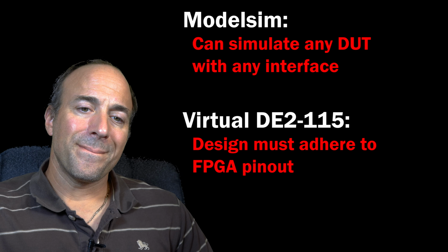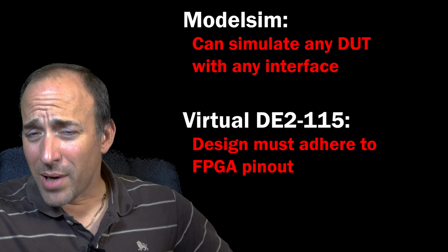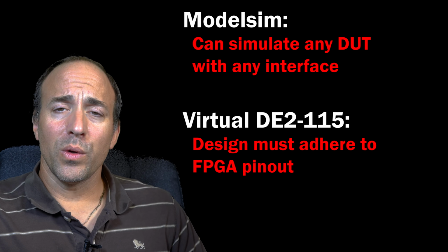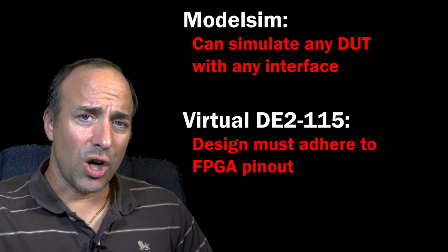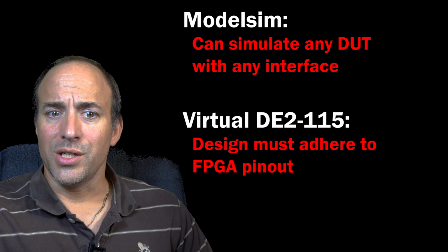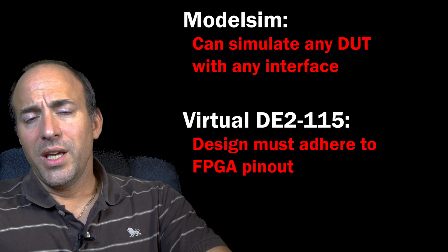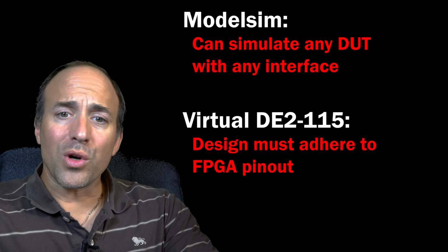However, simulating with Modelsim and simulating on the virtual DE2-115 use different methodologies. So using the virtual DE2-115 forces you, as a designer, to adhere to the conventions that are normally required when performing physical design.